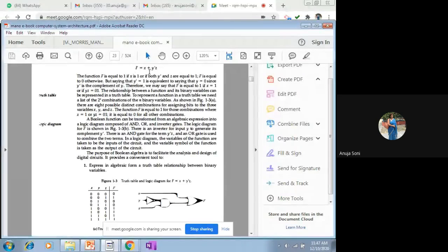The way you read out your Boolean expression step by step, in the similar manner you have to go on drawing this logic circuit diagram. First of all, you have to think about the logic operations. Logic operations correspond to the logic gates, and you have to count the number of gates required in drawing the logic circuit diagram.